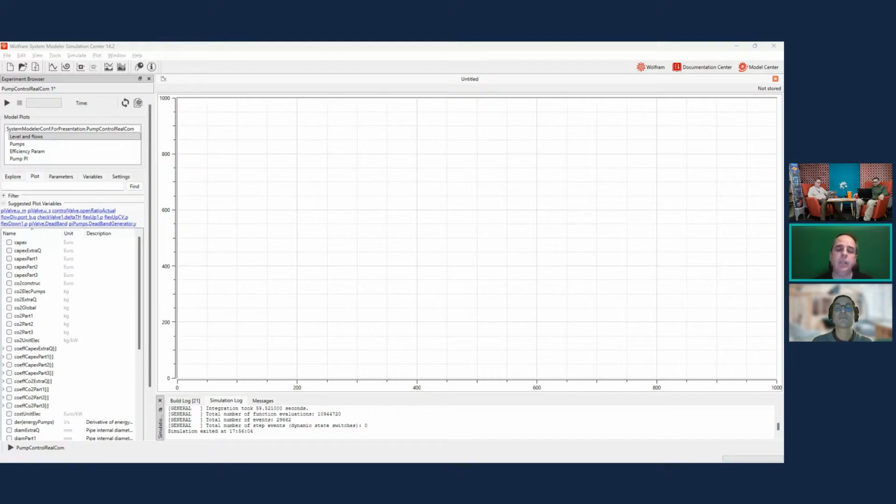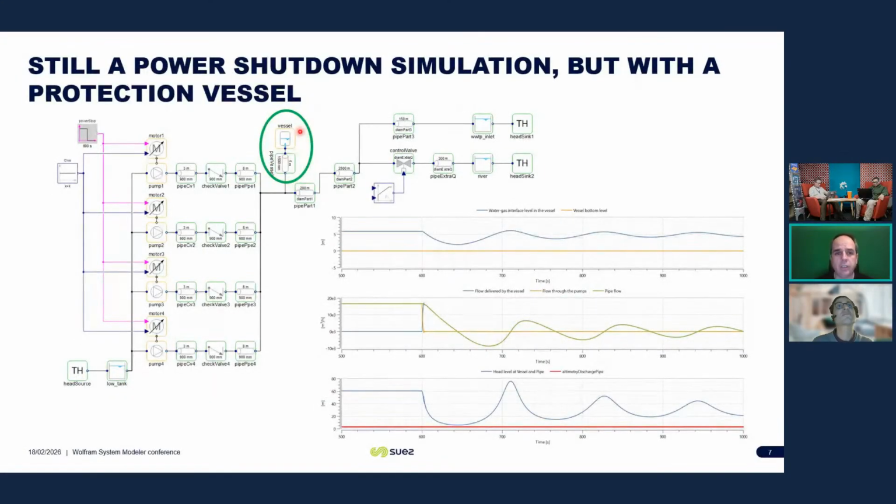So in this sense, it's to approach the vessel to the pumps that are the elements that change their condition upon power failure. If we place it further away, we are going to have the phenomena developing until it finds the vessel. And so we end up with two oscillation systems, one upstream the vessel and another one downstream the vessel. I don't know if this was the question.